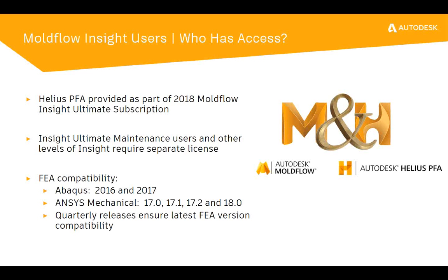Great. Residual stresses are tricky to account for. And the reason is we know in plastic parts residual stresses exist. That's the nature of injection molding, that's the nature of plastics. We get differential shrinkage, we get out of plane and in plane shrinkage, which could contribute to warpage. So we know when our part comes out of the mold and cools down, there's residual stresses there. We know that.